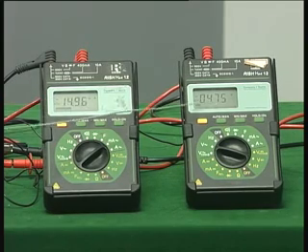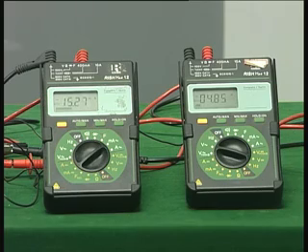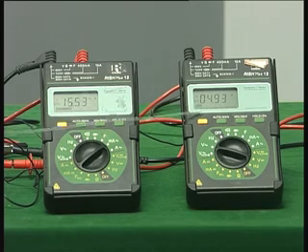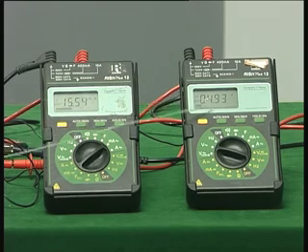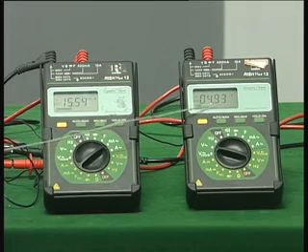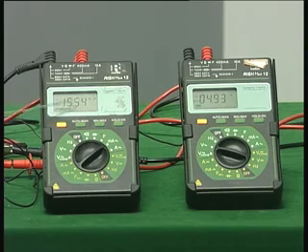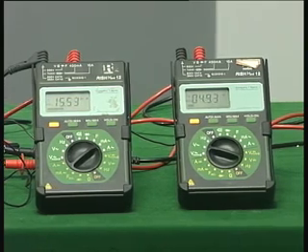Now you find it is around 4.7. If I go still further, for example 8.3, it is still around 4.8 volts. If I go to some 10 volts, you would find still it is around 4.9 volts. So irrespective of how I change the input voltage, the output voltage is not changing, it is remaining constant, very close to about 4.9, but the series current has actually increased enormously.